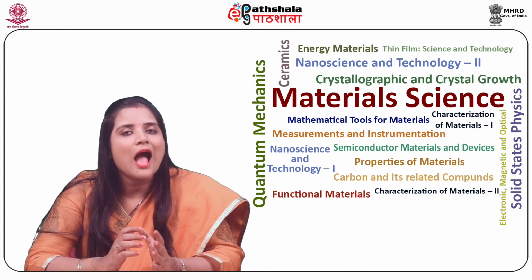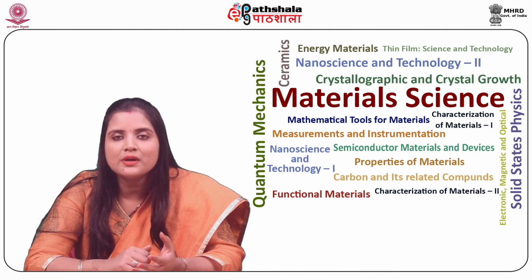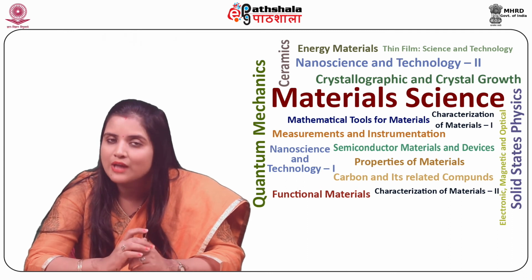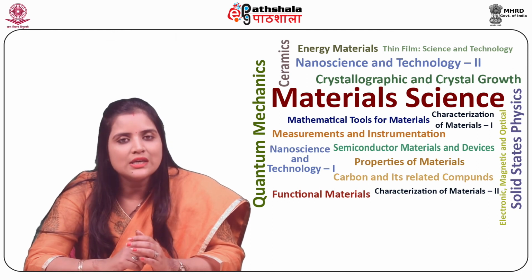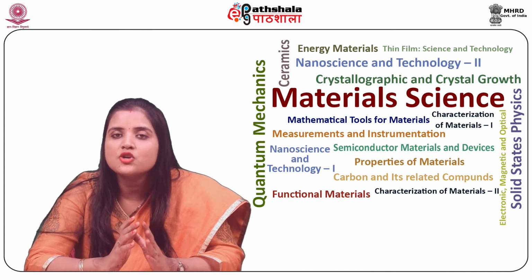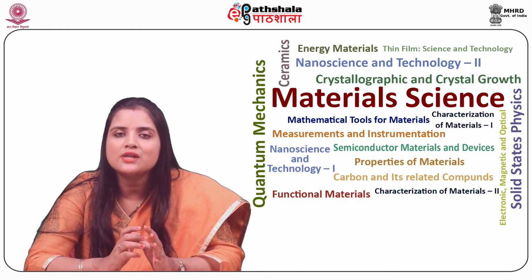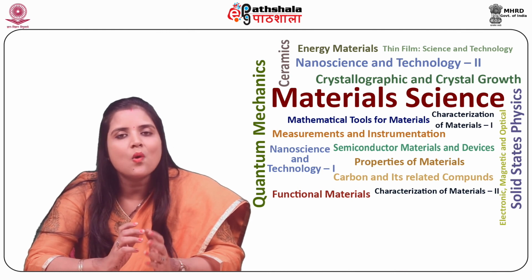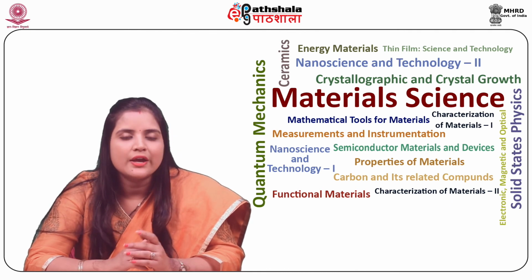Let us study the applications of electroluminescence. Generally, electroluminescence instruments can be produced from both organic as well as inorganic electroluminescence constituents. These electroluminescent active sources are usually semiconductors having large bandwidth, which allows light to transmit. A typical inorganic thin film EL, that is TFEL, is zinc sulfide doped with Mn, exhibiting yellow-orange emission. Applications of the electroluminescence materials include